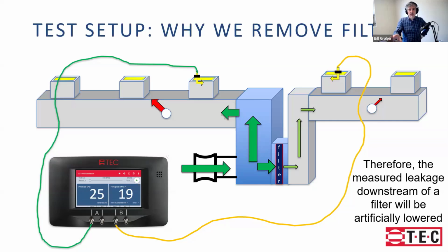This is helpful to me because it's a nice summary. I've had these discussions myself many times, and I think this is the clearest. One of the things that I think confuses people, similar to blower doors, is that it's not how it actually operates. Just like in a blower door, we pressurize it to 50, but it's not going to see that pressure. And so this is more of just a way of us being able to do QA work, quality work, to say, how tight is that duct work? It's not trying to estimate the leakage during actual operation. It's trying to say, did we seal this well? Is that correct? Is that the right way to think about it?